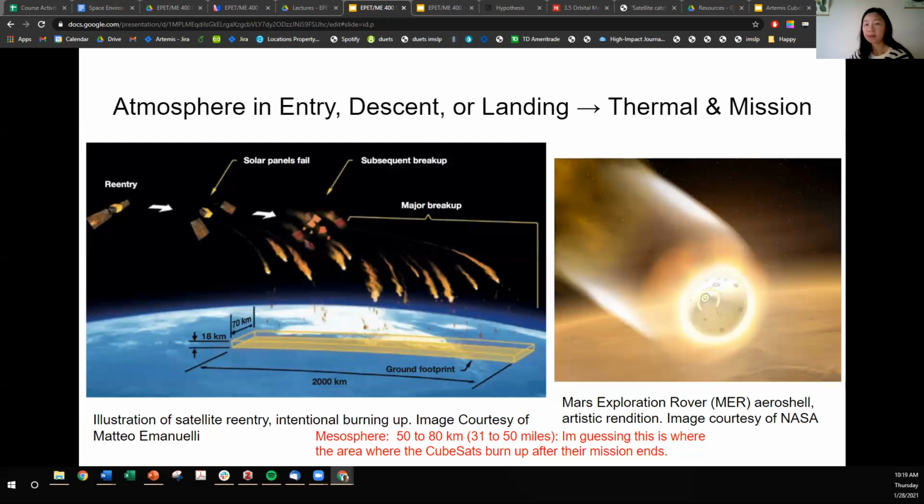Every object in Earth orbit below the 1,000-kilometer altitude is subject to atmospheric drag, which will decrease its energy and slowly reduce altitude in a spiral that will eventually cause it to re-enter the Earth's atmosphere. Objects with an initial altitude of 1,000 kilometers may take centuries to complete this process. However, objects at 500 kilometers will normally decay within about 10 years. And the average object at 200 kilometers will decay within a very few days. Uncontrolled objects reach high velocities while accelerating through space toward the Earth under the influence of Earth's gravity and are slowed by friction upon entering Earth's atmosphere.